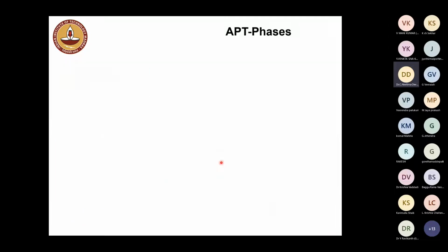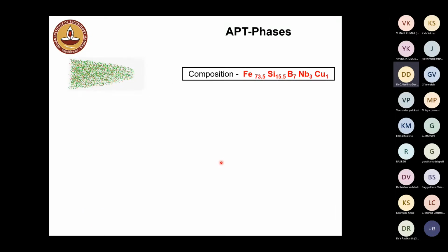Now imagine that this material is in the as-prepared condition. That means it is in the original amorphous state. If you look at the amorphous microstructure, or the distribution of elements in the amorphous state in 3 dimensions, all the atoms look randomly distributed. But in the application, we need to have defined nanocrystals from this random distribution, and therefore we need to generate nanocrystals by one of these annealing methods.